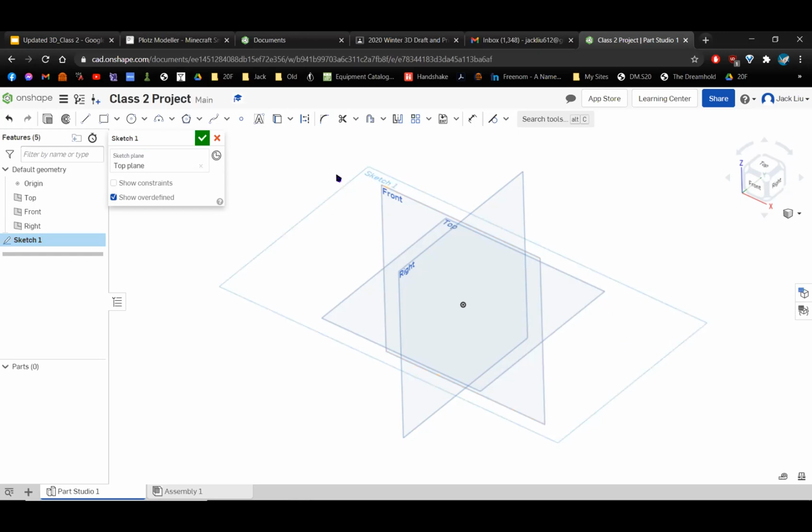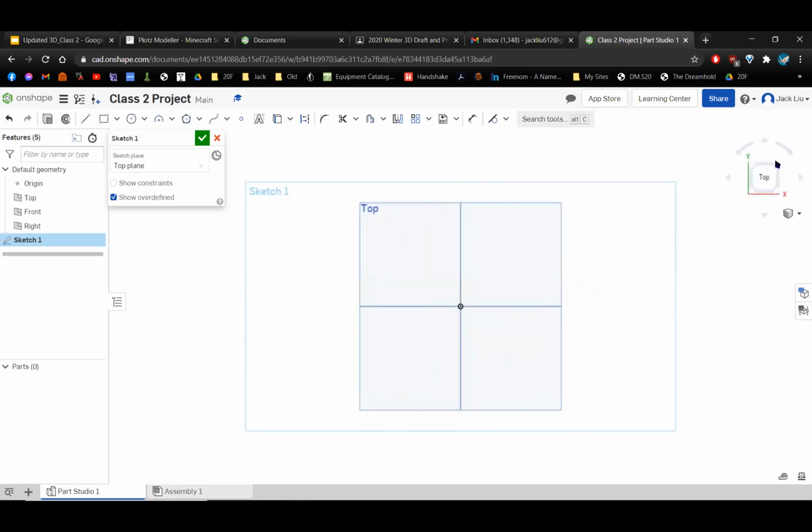This creates a sketch for us to draw our shapes on. And I'm gonna move my screen back to normal. So I right click view normal to sketch plane, this last option. Or you can use the cube to manipulate the view. But now we're looking down again and we're ready to start drawing, start CADing.